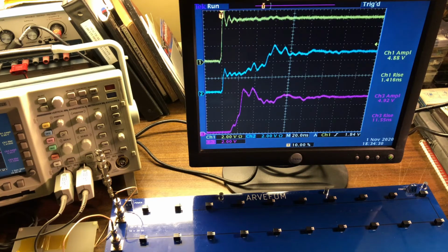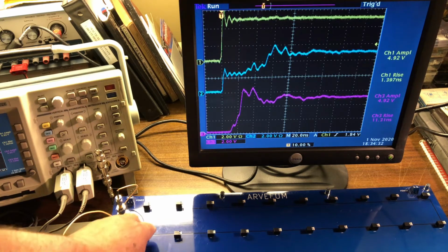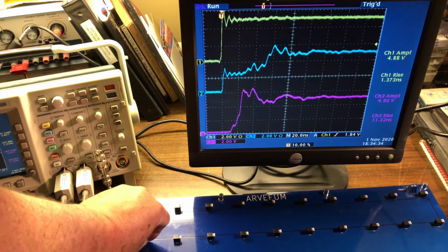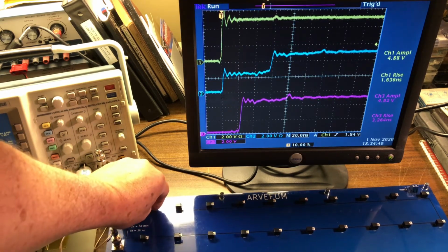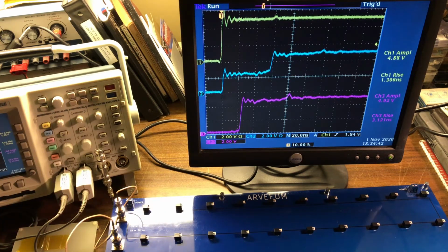What you really need, and I'll fix it here, is just the ones where the signal comes into the line that is using a power plane. See, that got much better. And then where it exits. So you only need pretty much 2 caps next to the line.